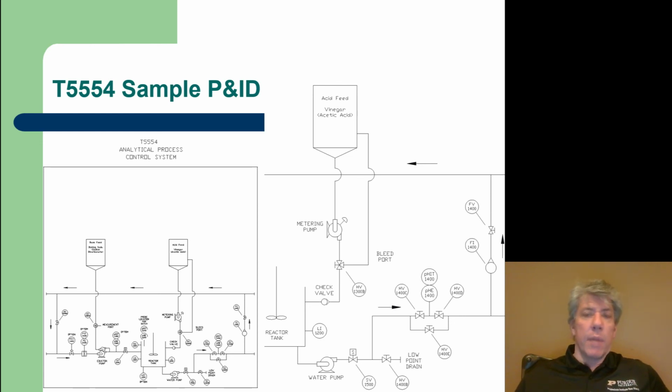Well, if you're operating a wastewater treatment plant, you probably can't shut off thousands of gallons going through per minute or per second, and so what you've got to do is somehow have a bypass, and that's the way I set this up. So there's a bypass network where in normal operation HV 1400E would be closed, and HV 1400C and 1400D would be open, but to change out the pH element, the sensor itself, what you would do is you would open HV 1400E and then close off C and D, so that the pH element is isolated from the rest of the piping line.